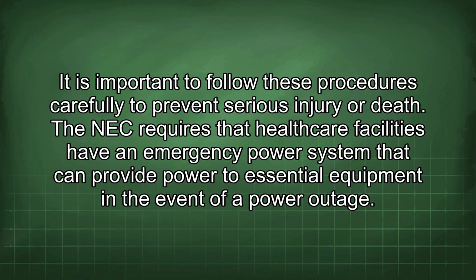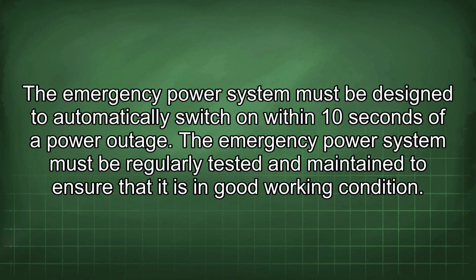The NEC requires that healthcare facilities have an emergency power system that can provide power to essential equipment in the event of a power outage. The emergency power system must be designed to automatically switch on within 10 seconds of a power outage. The emergency power system must be regularly tested and maintained to ensure that it is in good working condition.